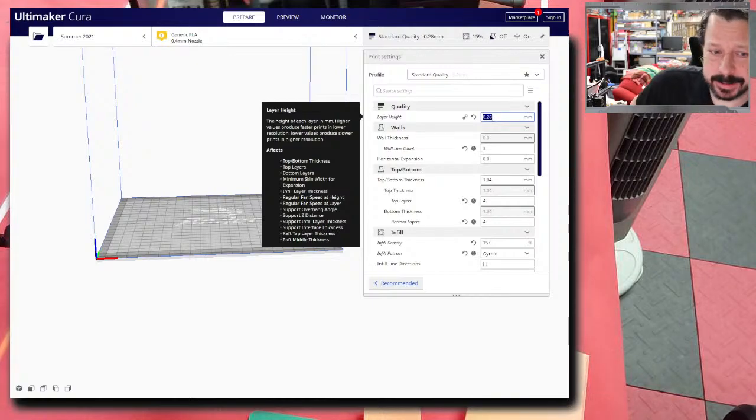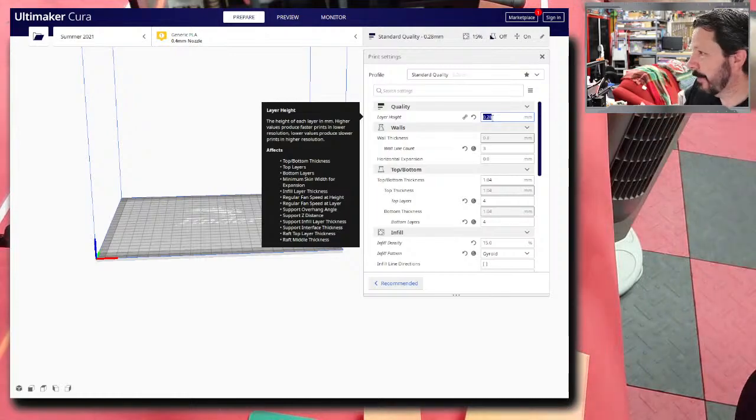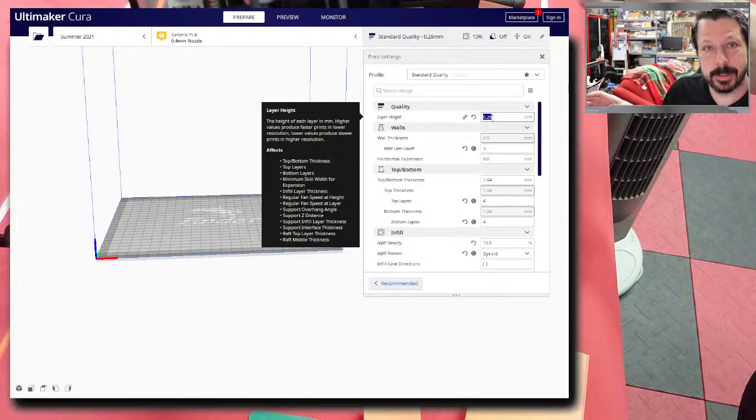Another thing, I didn't mention this: if your prints are suffering from not cooling well enough, put a fan that blows across the entire print bed. Now this will affect your hot end also because it's going to be cooled by that fan. But most hot ends today have a silicone sock around them and they're pretty well shielded from drafts. That fan blowing across the whole print bed will help cool the parts. And I've had decent success when a part was just too thin or it just wouldn't cool very well, just putting a fan blowing across the print.